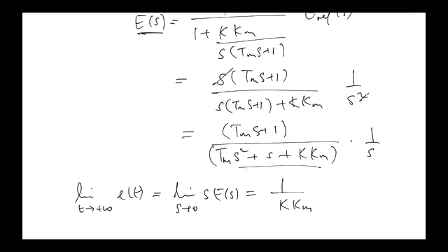Are there any questions on that? Yep. Is the system already marginally stable because of 1 by s? Because of what, sorry? The 1 by s? That's open loop, in open loop, right? What we've analysed now is the closed loop system. The closed loop system is stable, right? The closed loop transfer function from the reference to the error signal is stable, right? It's this transfer function here. It's got the same denominator as here.